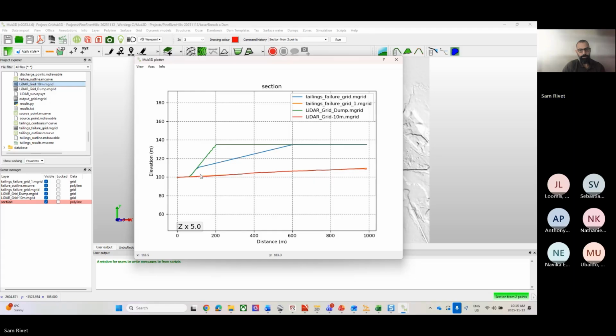But we can see here, at 110 meters, 5%, this entire corner here shears off. And I believe what we're seeing here in terms of this first surface, failure grid 1, or the 100-meter failure at 1%, is basically this entire piece of the dump fails.